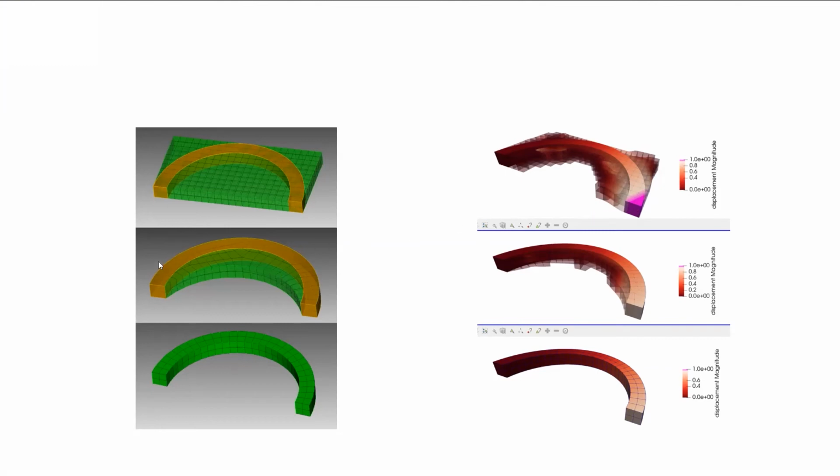Another scheme would be to fit this outer boundary with a body fitted mesh, but not worry about capturing this inner surface. And then there's a traditional body fitted spline. Effectively, fitting this one extra surface but leaving the other surface completely immersed is essentially indistinguishable. There's less than 1% error between these two bottom pictures. Yeah, it's a little bit more than 1%. But the top picture had over 30% error.